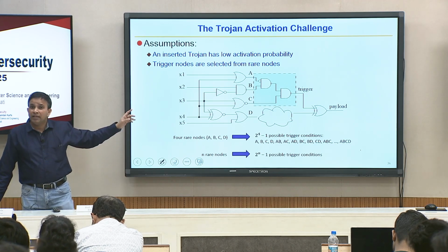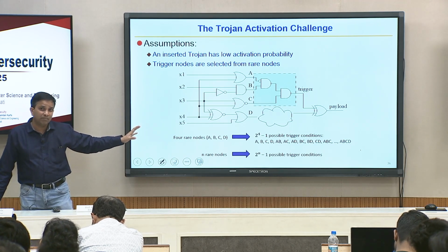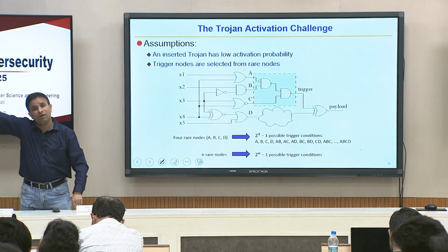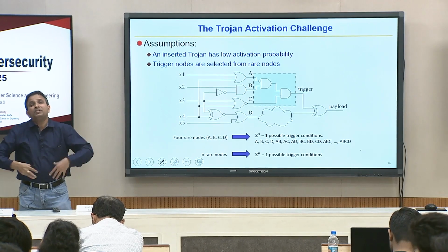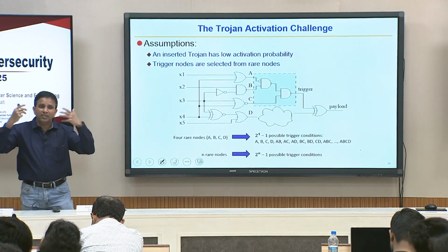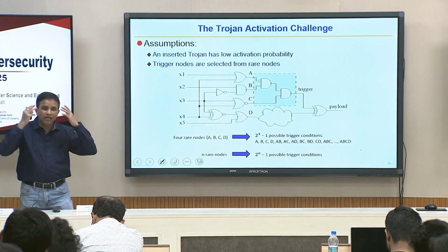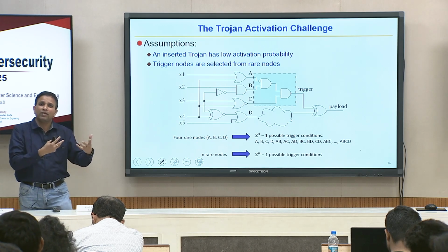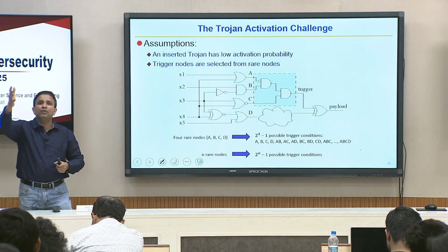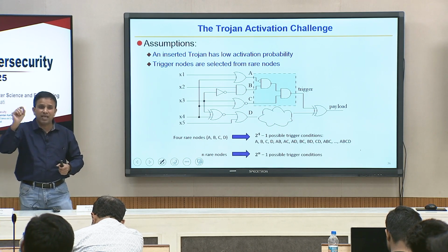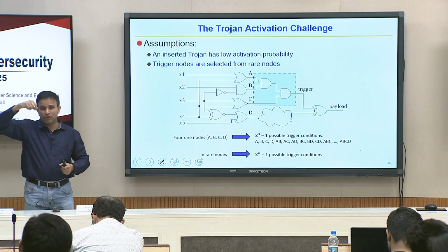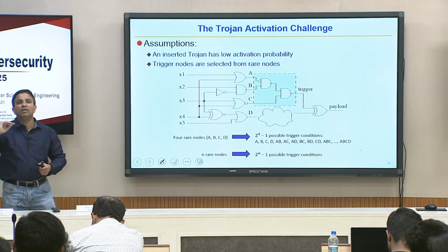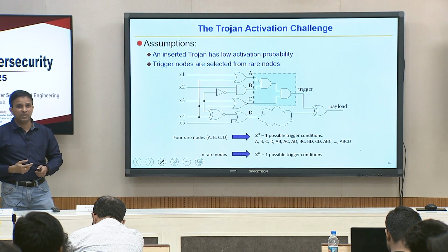And remember, this is what we are doing at design time. The Trojan might not get inserted in design time; it may get inserted during fabrication time. So, you want to generate tests now, so that after fabrication, when the chip comes in, you can run the tests, exactly the way the manufacturing defect story works. You want to create manufacturing tests even before it goes for manufacturing. When it comes in, you keep running those tests and say, oh well, that wire was drawn correctly, that transistor is formed correctly, tick, tick, tick. You do this for all of the millions of lines, same analogy.